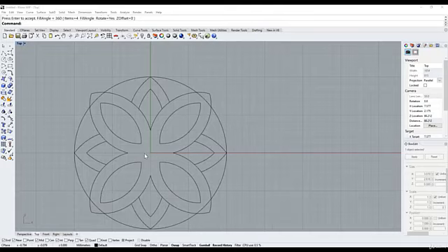this design. So come over to here, hit this rectangle, and if I click anywhere and hold shift, that's going to constrain it into a square shape. If I'm not holding shift, that will allow us to make a free rectangle. So I'll hold shift and just drag that out. If I want that to be, say, 1 millimeter, I can just type 1 and enter. And then if I type enter again, it's going to use the length as the width. So it's going to make it square.